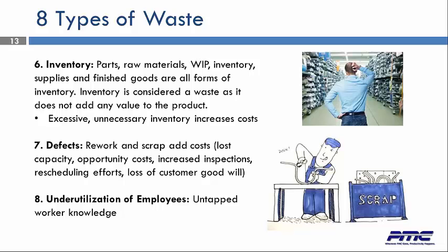The sixth type of waste is inventory. Anything that is extra in your plant or your facility is your inventory and naturally occupies space in your facility, which obviously increases costs. So excessive unnecessary inventory increases costs. The seventh one is defects. Rework and scrap adds costs like lost capacity, opportunity costs, increased inspections, rescheduling efforts, loss of customer goodwill.